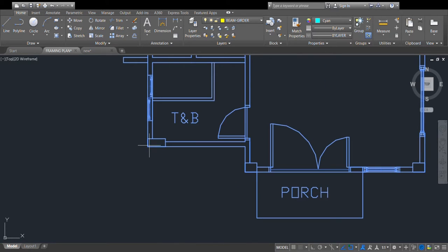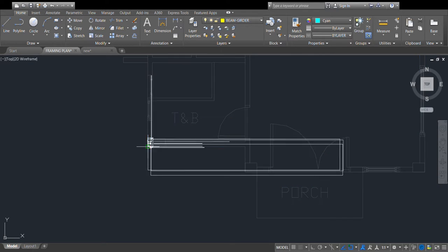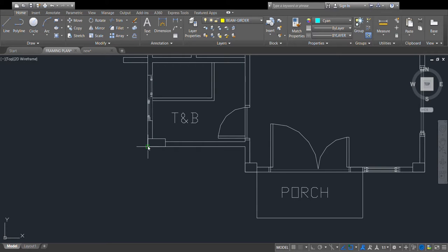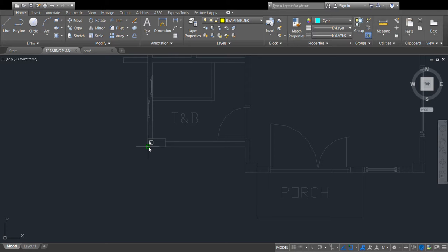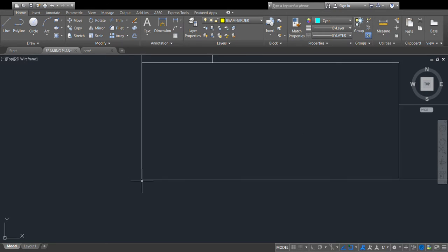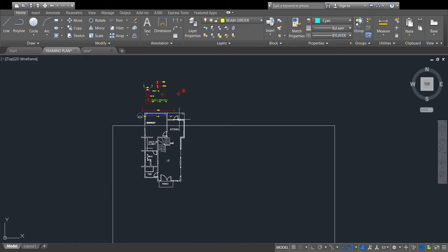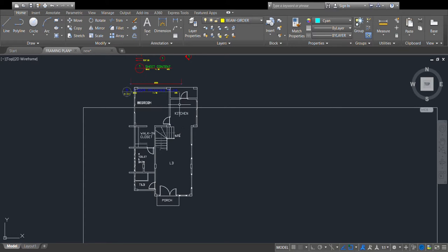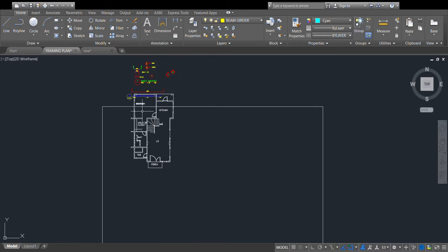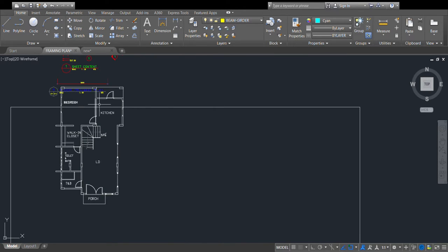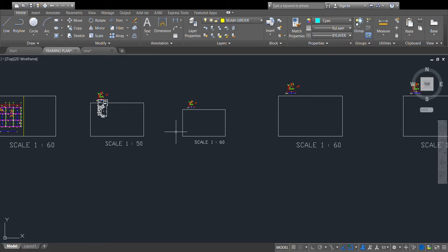Select the lower left corner of one of your drawing, and then press R. Your scale factor is 1. Your new length is 1000. So if you're going to zoom this further, tada! That's actually the scale drawing. But it is quite an obvious thought that this is very small relative to this workspace. So you're going to use another scale for this one.